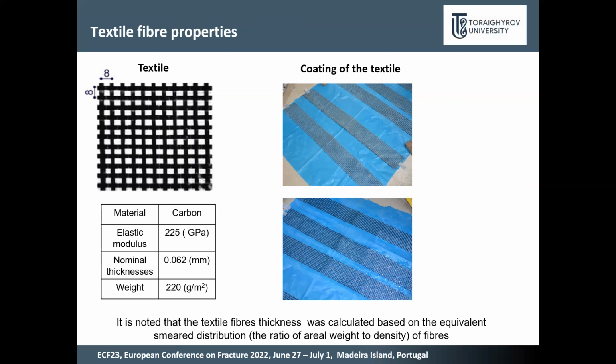Then the textile was placed flat onto a workbench, taped to prevent slip, and painted using a roller with a foam nose. The textile was left in a lab for 2 days to cure, and only after that moved to strengthening.